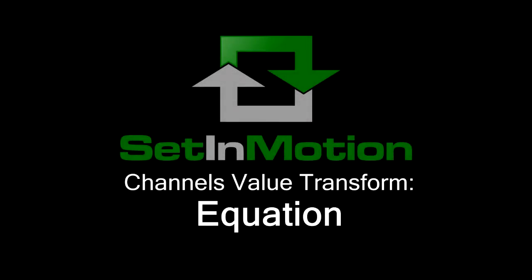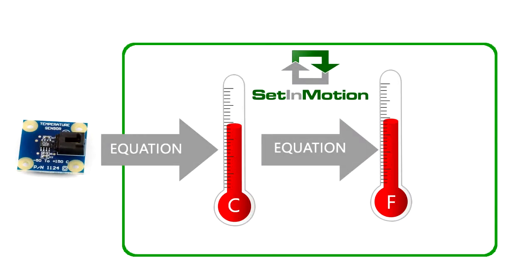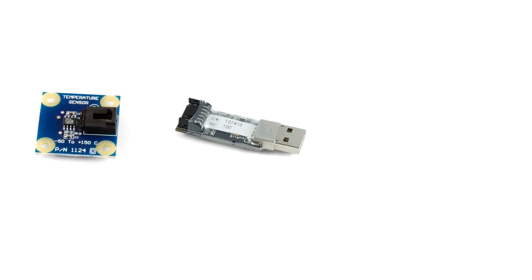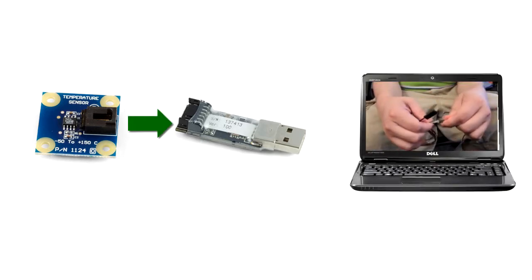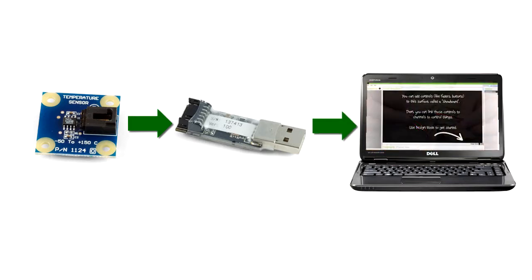In this tutorial, we'll show you how to use the equation function of a value transform to convert the output of a temperature probe from Celsius to Fahrenheit. For this demonstration, you'll need any Phidgets interface kit. I'll be using the 2x2x2 and a Phidgets 1124 temperature probe. Plug the temperature probe into an analog input on the interface kit and connect the interface kit to a USB